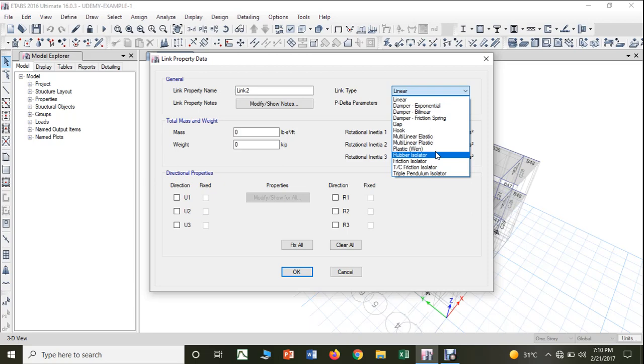So by deviating them, it will not make the earthquakes transmit into the buildings. It will avoid it. Either it will absorb or it will deviate. Therefore, whatever energy is transmitted in the soil through the waves will not be transferred to the buildings. So the building will be safeguarded.